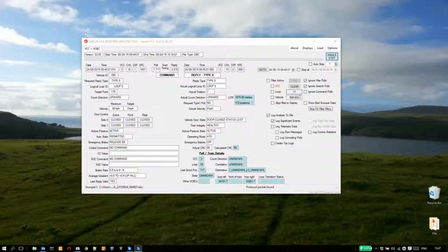First of all, I'm going to start off by clearing my current command and response filter, and then I'm going to right click on my vehicle ID and left click in this box here, and then enter the numbers 66, then left click on add, left click in the box again, 87, then left click on add, and it's added it to our vehicle filter.